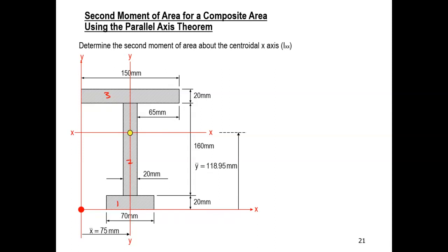So does this composite shape have its own coordinate system? The answer is yes. The composite shape coordinate system should be located at its centroid. So the first step for finding the second moment of inertia of a composite shape or compound shape is to find its centroid.